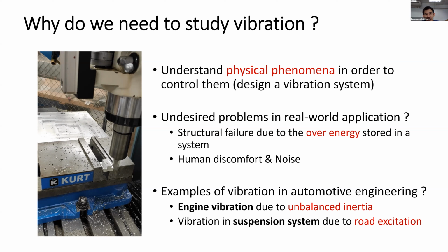The vertical excitation from the road, 5 centimeters, doesn't need to be transferred to your seat. Many times, if you drive at a certain speed, you cannot even feel that 5 centimeter obstacle on the road, if the engineer can fine tune the spring stiffness and damper for the operating speed of your car.